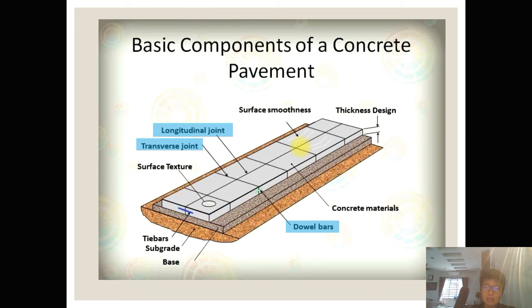And one more thing is that when you are casting concrete, as we learned in concrete technology, for a big slab or a big element, you can't cast it in one go. Why? If it is so deep, the concrete at the bottom starts to set while the top has just been poured. The setting of concrete, because of the cement, is exothermic, meaning it exudes heat. Imagine you pour the first layer, then the second, third, and fourth layers.